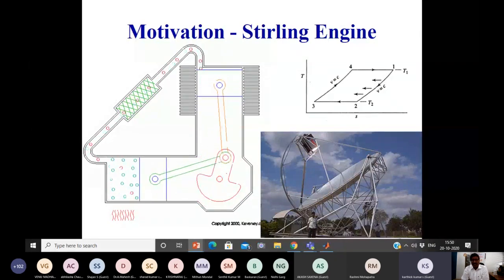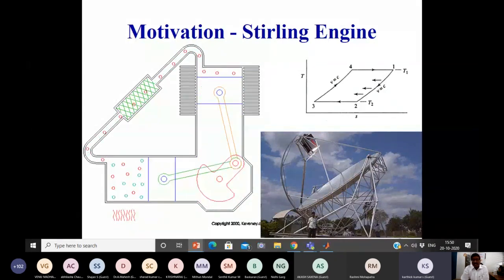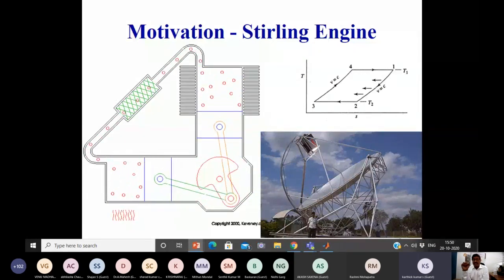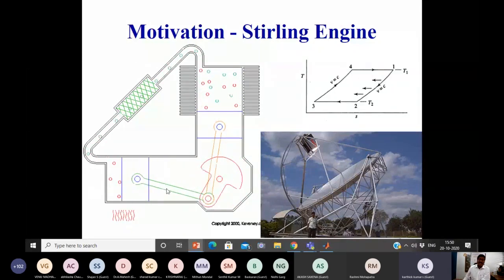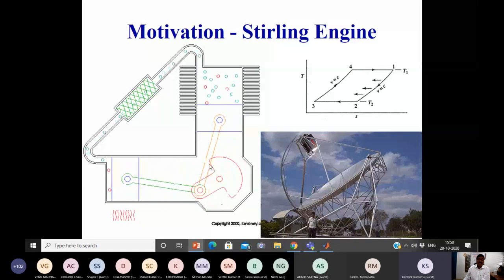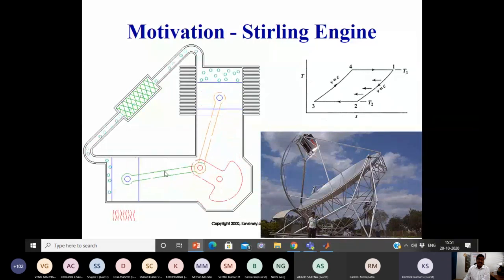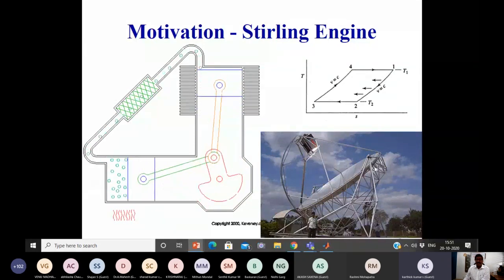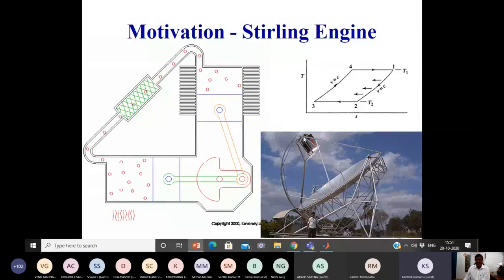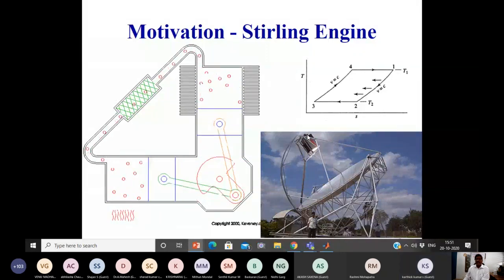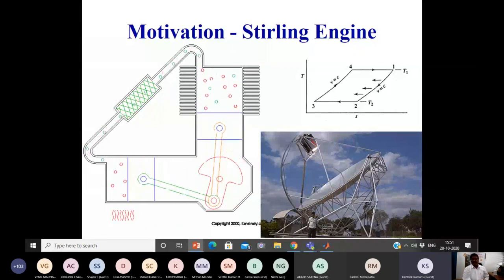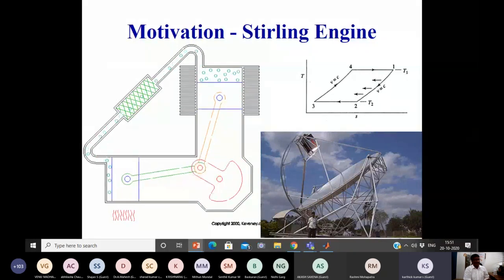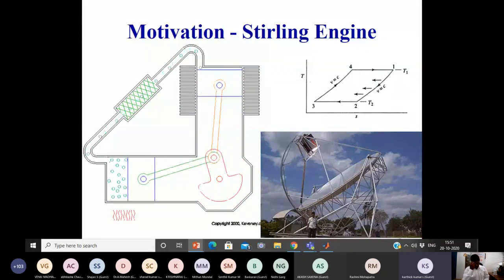We had a 9 kilowatt solar machine at our earlier university. This is a 9 kilowatt Stirling engine. The Stirling engine works with helium as the working fluid. See the Stirling cycle. On the other side, this is the engine. Two engines or pistons are working here. The heating side is heated by focused solar energy at this focal point. The other side of this engine is the heat rejection, the water-cooled condenser. Unfortunately, after 6 months this water-cooled condenser corroded and water leaked, and gradually the engine corroded.